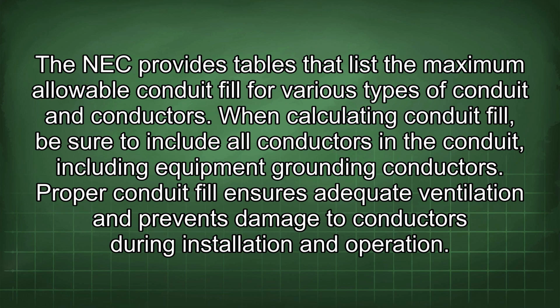When calculating conduit fill, be sure to include all conductors in the conduit, including equipment grounding conductors. Proper conduit fill ensures adequate ventilation and prevents damage to conductors during installation and operation.